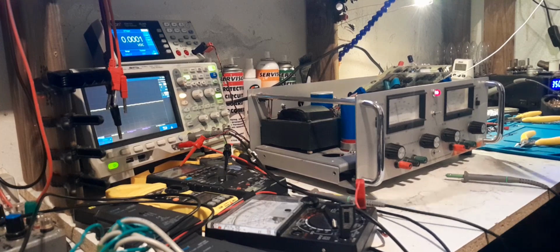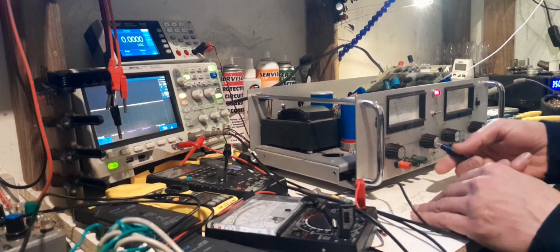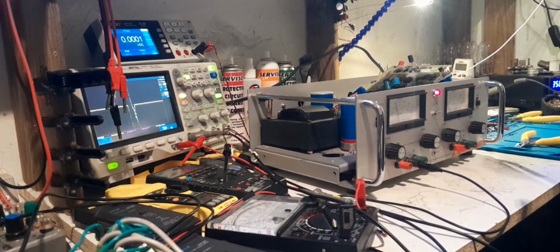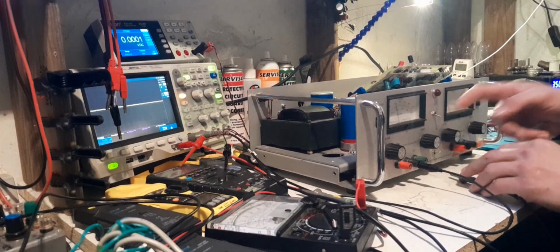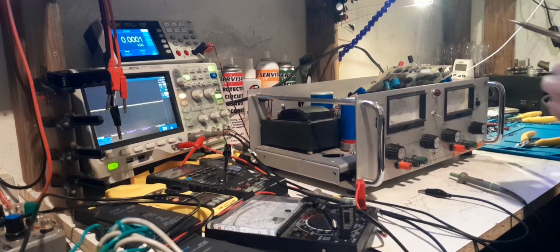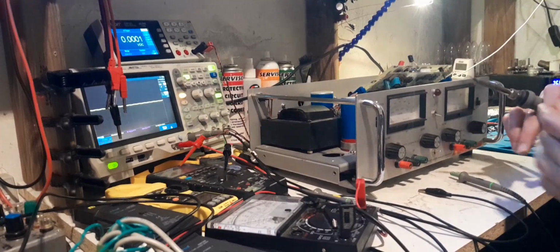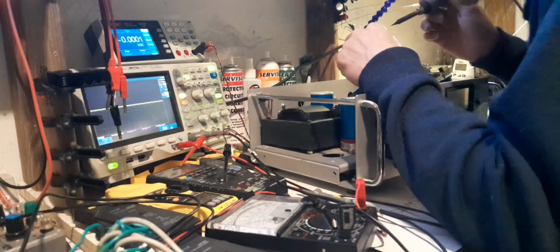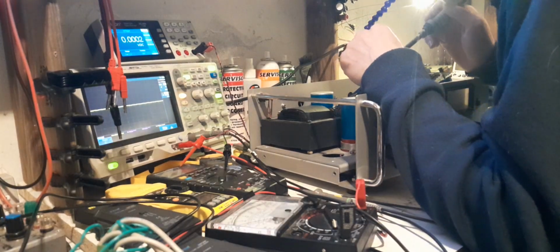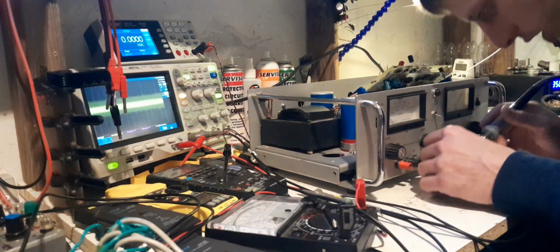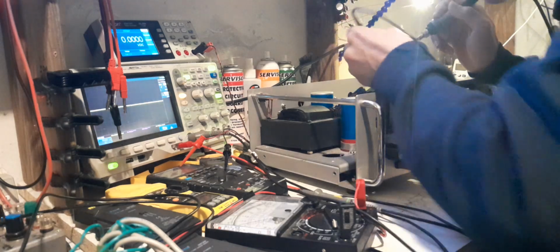Right, where are we? So I want to be grounded to here. This is my probe that I've got. I'll turn this off, take that off. Don't want to make that mistake again. The reason I disconnected the ground probe, even though it's off, is because capacitors are still discharging in here, and it would not be good if there was still voltage on here and I shorted it and popped something.